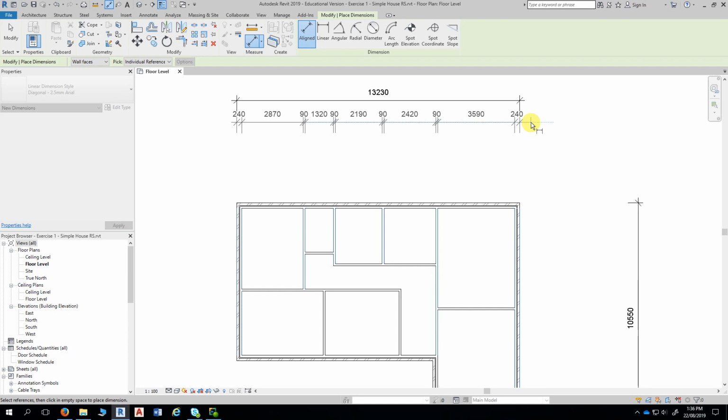Yep. Now, when you're doing it for yourself, you'll see it on your own screens. You'll actually see at a certain point, you'll feel it stick. And if you move left and right, you'll see a blue dashed line. That blue dashed line is indicating the correct position of that second dimension. And what that allows you to do is get your dimension spacing correct.